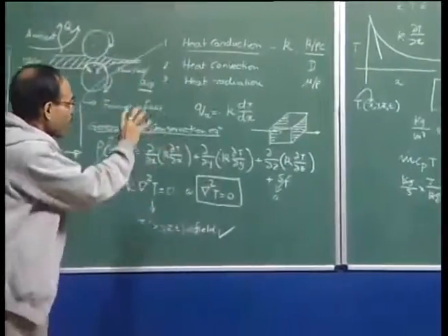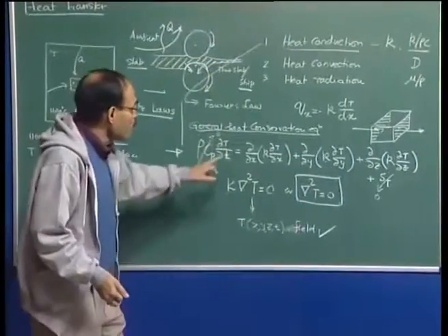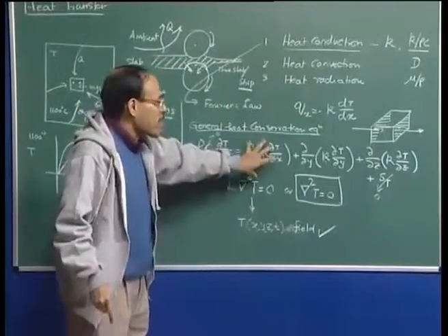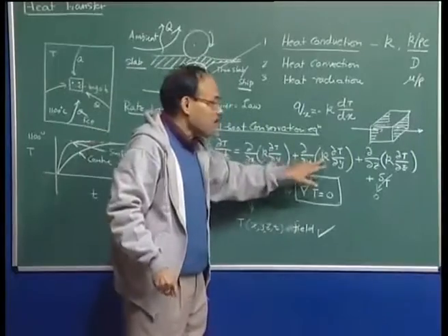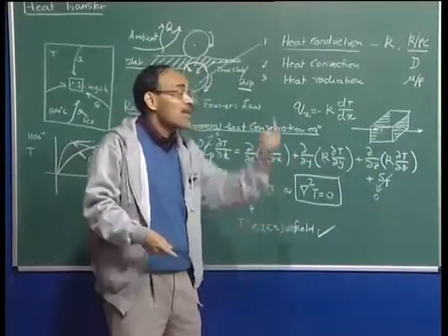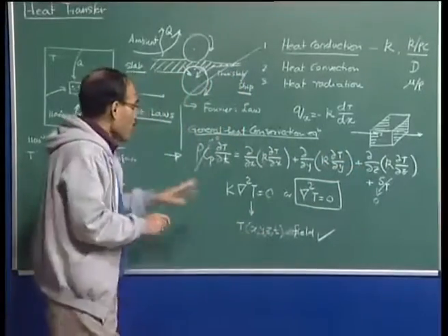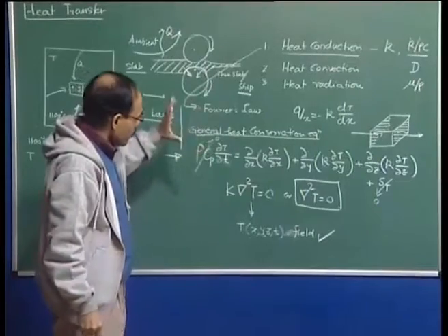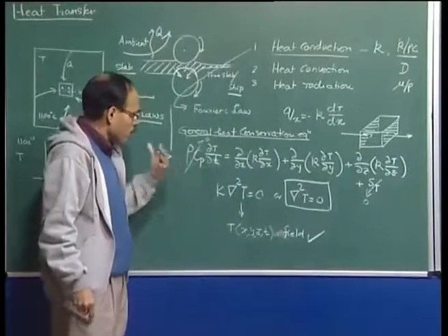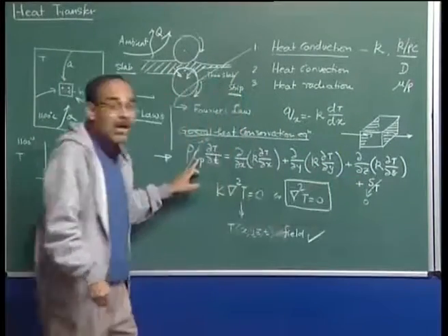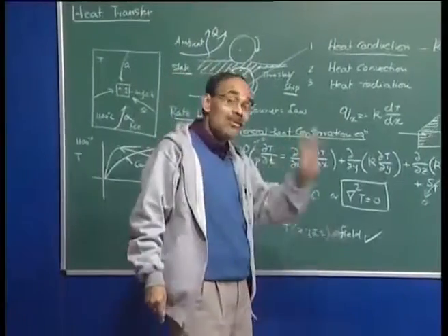So, we can understand that if I have to write an energy balance equation for a fluid element where heat is flowing because of both conduction and convection, I will not have 4 terms on the right hand side, but I am going to have 7 terms. In the x direction, one conduction term, and on top of that, heat will be flowing by convection also. In the y direction, heat is flowing, for example, here only due to conduction, but now I am talking of a fluid element, so in addition I am going to have convection, and so it is in the z direction. While a reasonably realistic governing equation for a control volume with heat flow due to conduction may contain only 1, 2, 3, 4, 5 terms, if I am talking of conduction plus convection as the 2 modes of heat flow, I may have 5 plus 3 more terms, altogether 8 terms.